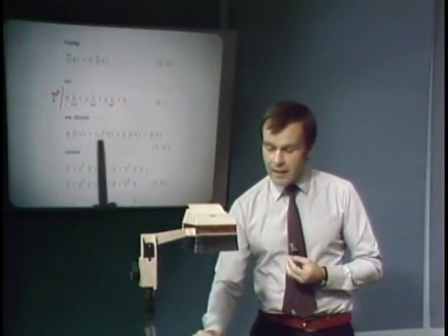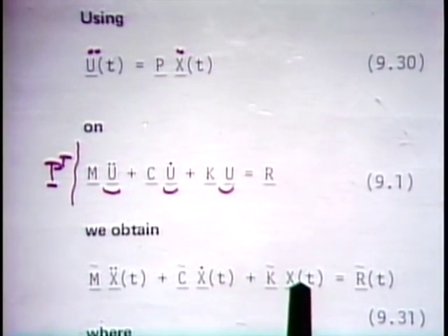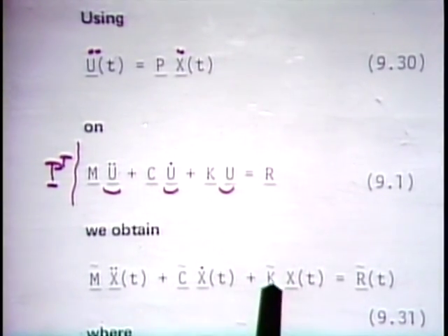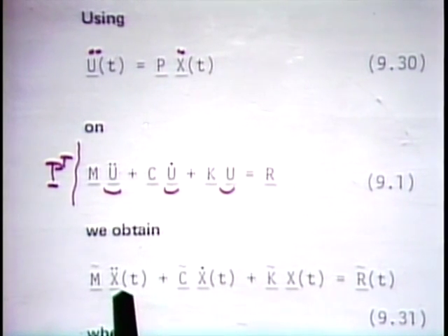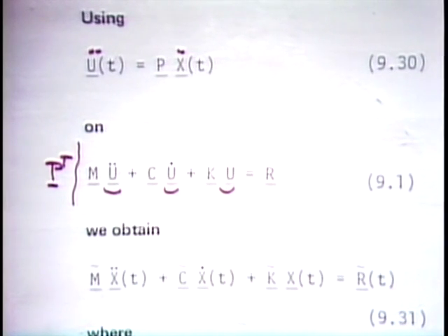Once we have diagonal matrices here on the left-hand side, in other words, M curl, C curl, and K curl, then we can use our direct time integration schemes, the Newmark method, or the central difference method. Usually we use the Newmark method. Or we might even be able to solve the decoupled equations. They're decoupled because M curl, C curl, and K curl are diagonal.